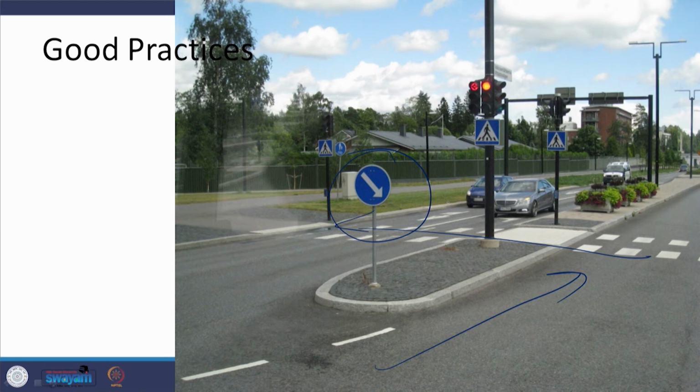All these vehicles are stopping ahead of the pedestrian crossing. There are arrows which define that if you have to go straight or in some direction, then in which particular lane you should be. The pedestrian crossing markings are there, and at this location signals are also placed. So, signals and the markings have been placed at the same pole, and there is a gap in the median because the pedestrians are going to move at the same level as the carriageway. So, this is another sort of design which is quite good and conducive for the users.